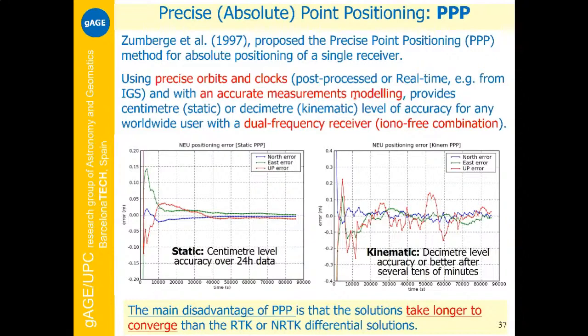Even with the solid tides. What does it mean, solid tides? Solid tides means that the solid surface of the Earth is moved due to the sun and moon attraction, like the water, like the oceans. And this can vary by up to 20 centimeters. And then if we want to achieve absolute positioning with centimeter level, we have to account for this up to 20 centimeters. Then we have to model everything as much as possible.